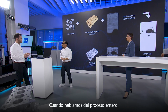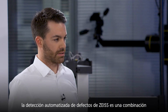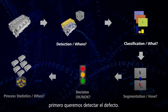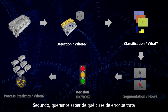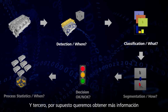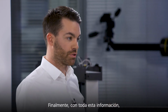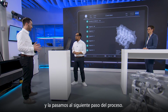But that's not all. When we're talking about the whole process, the Zeiss automated defect detection is a combination of artificial intelligence and an easy-to-adapt decision scheme. When you look at the screen, first we want to detect the defect. Second, we want to know the error class. Is it a pore, is it rest sand? And third, for sure, we also want to know more information about the specific defect, so volume, size and maybe the form. And at the end, with all this information, we can decide if this is an okay part or not okay part, and we pass it through to the next processing step.